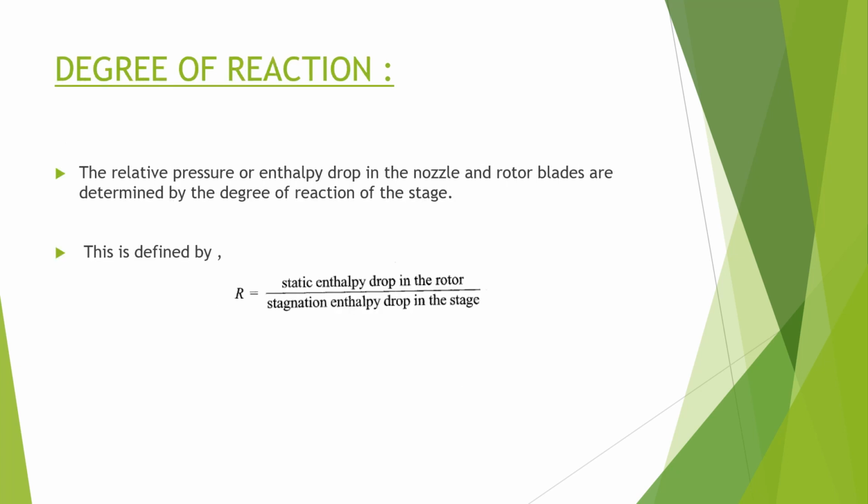And the next topic is degree of reaction. The relative pressure or enthalpy drop in the nozzle and rotor blades is determined by the degree of reaction of the stage, which is defined as R equal to the static enthalpy drop in the rotor divided by the stagnation enthalpy drop in the stage.